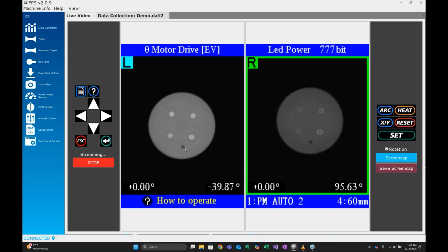So we've got a good visual here. Okay, I can inspect this. I can see the polarity of this fiber, right? I can see here's my marker, here's core 1. Right, and then I can use this to mark my polarity. Okay, this is core 1, 2, 3, 4, and this one matches. This is my 1, 2, 3, 4. If the marker was over here and I lined my cores up, then I would have core 1 going to core 4, right? And likewise, core 1 over here going to core 4 over here, right? That's your typical polarity scrambling from a multi-core fiber, right?